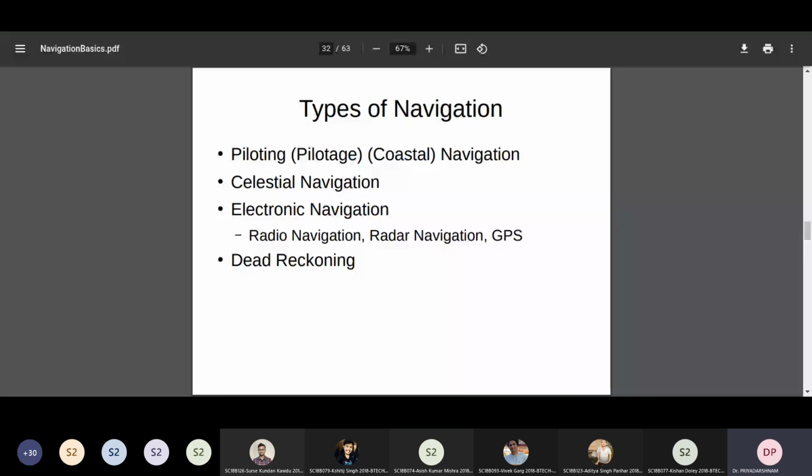The guidance path you use will depend on the application at hand. You may minimize the distance or fuel, or optimize your path with respect to some constraints. Control is nothing but the steering commands, which also includes the thrust levels.